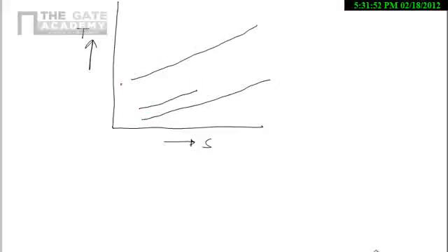So now from 1 to 2 we are in the diffuser. 1 to 2 and 2 to 3 there is a compression. But here in our problem we are considering the diffuser as a part of the compressor. So 1 to 3 there is a compression for us. 3 to 4 we are having the constant pressure heat addition.